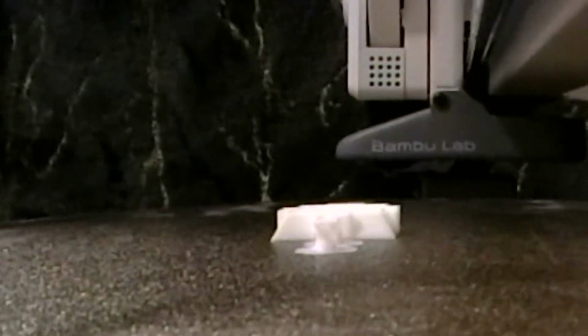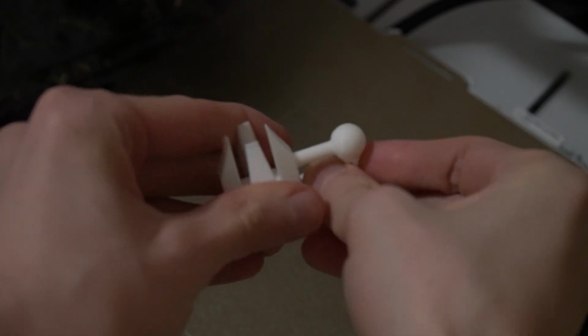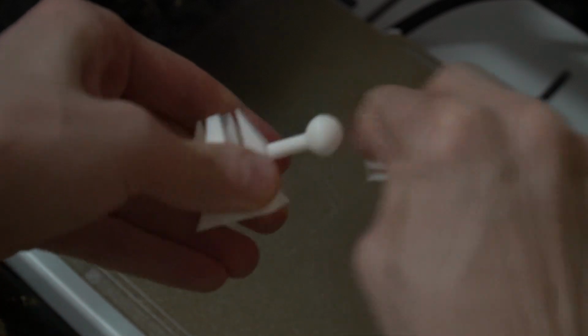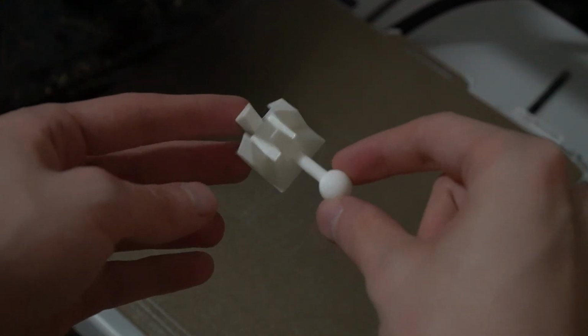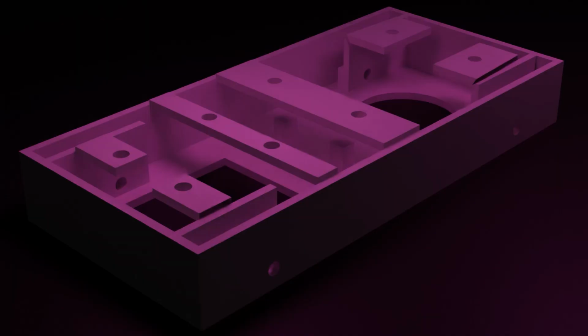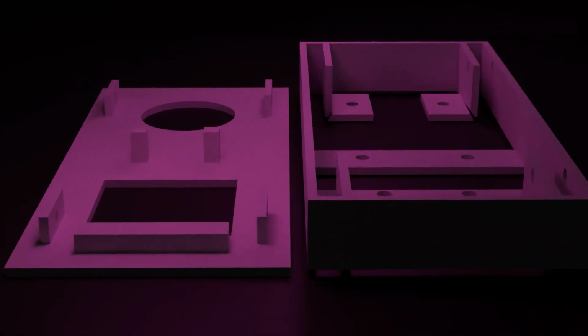Now this problem isn't unfixable, and you could just add some supports like this, and then yeah, it's completely printable, you can easily detach the supports, but we won't be dealing with that, it has its own problems. And instead, one thing you might notice is that if you take this cover and the sides, flip the sides upside down, then you can see that there are no hanging parts. That's why I switched from the screws on the floor to the screws on the sides.